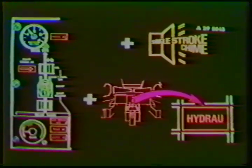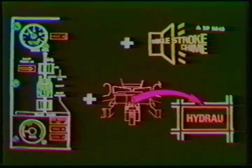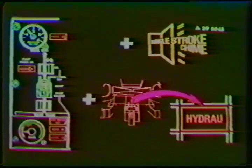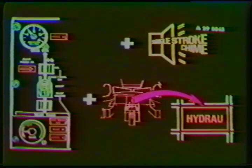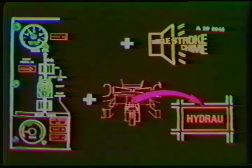For example, the blue system indicators are shown here, reflecting a low-level condition. The quantity gauge needle is pointing to the red dot in the yellow arc. Triggering of the warning circuit causes the level low light to illuminate, the hydraulic light on the master warning panel to illuminate, and the single stroke chime to sound.